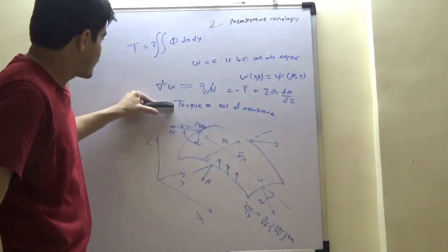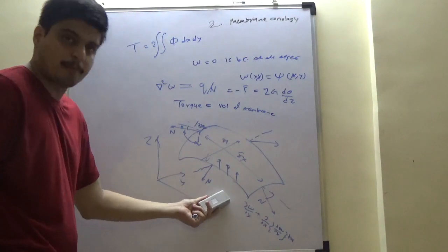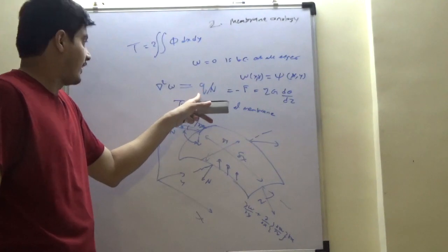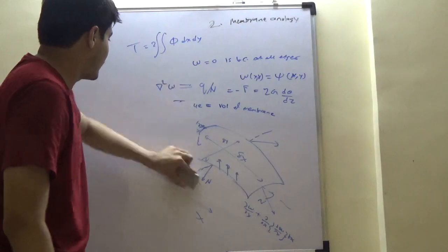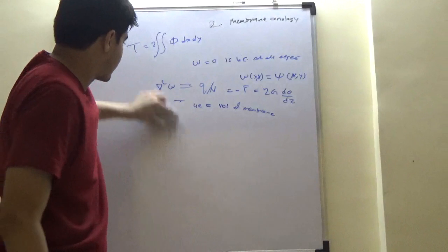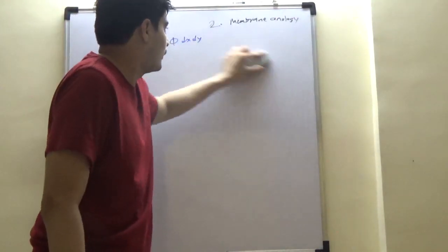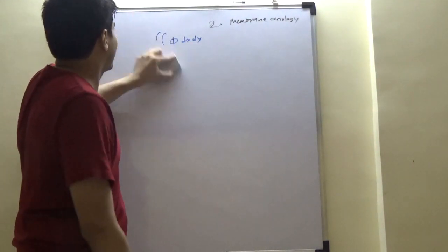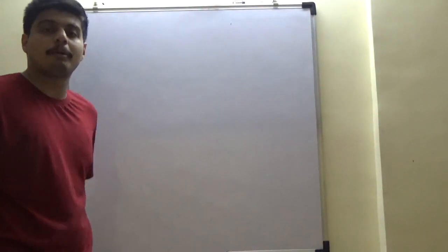So you have transformed a first set of problems into a completely different physics of a second problem, which are mathematically superimposable. This is much easier to handle, right? Because unit loads Q by N are very easy to handle without looking at any other complexity. So you have transformed your physics problem into a mathematics which is repeatable in other physics with the same consistent solution, and you can transpose back W as psi and solve your torsion problem. So that was the membrane analogy, a very powerful analogy by Prandtl.